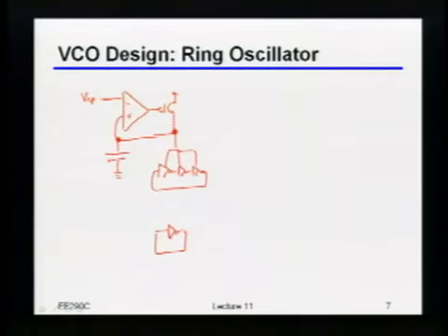Is it because the metastable points of the 3 inverters are not the same? No, not exactly. So let me give you a little bit of a hint. Let's say that somehow magically I get an edge into there, right? What do I want to make sure happens if I want this loop to actually work? With the single inverter, the gain of the loop is less than 1 because you won't actually fully charge back. Okay, so you kind of went in the direction I'm getting at, but I'm going to say it in a slightly different way, because you still use terms like gain, and remember, I want just the digital explanation. So you want that edge to go sufficiently high up before it feeds back.